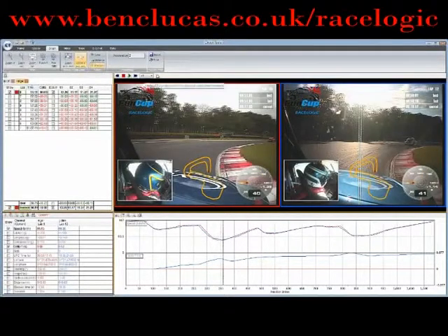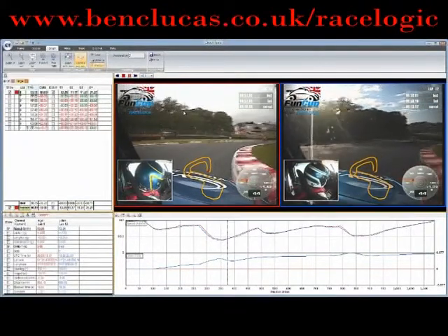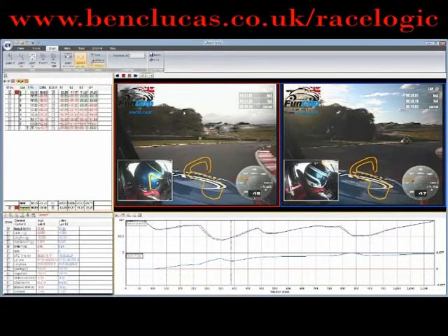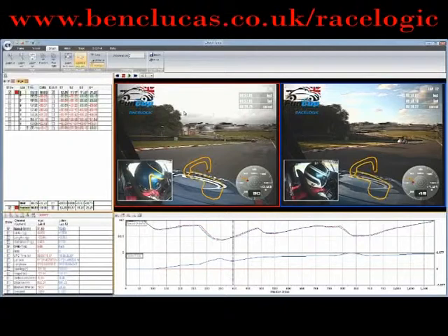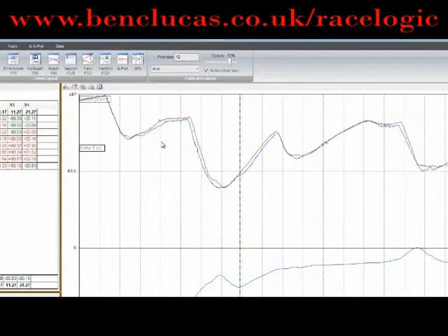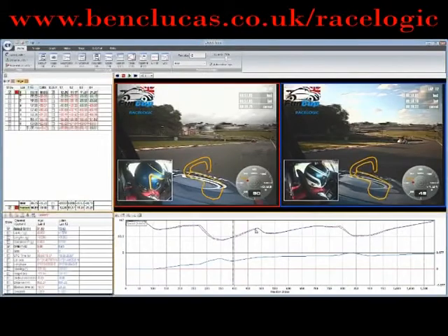Moving the video to the apex and playing in slow motion, you can clearly see that the faster driver holds onto the apex for much longer, and the slower driver drifts towards the outside of the corner. This means that the slower driver has to back off the throttle slightly in order to stop running wide, which can be seen in the blue speed trace. This results in 0.1 of a second loss by the braking point for the next corner.